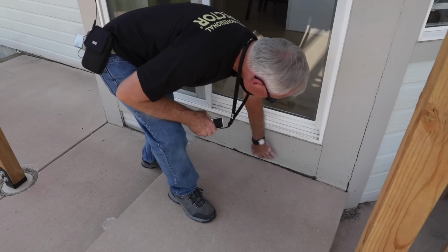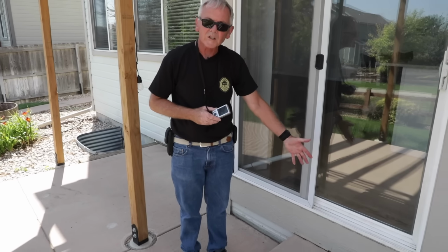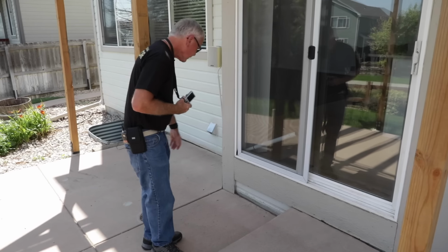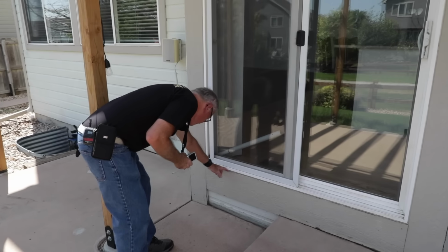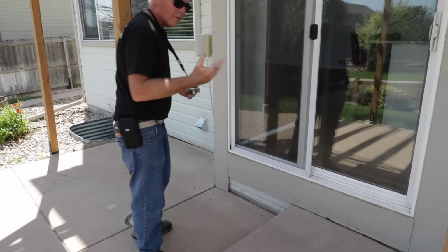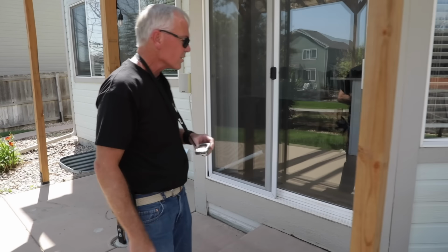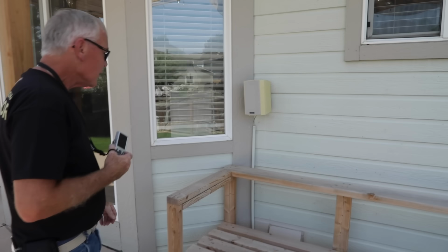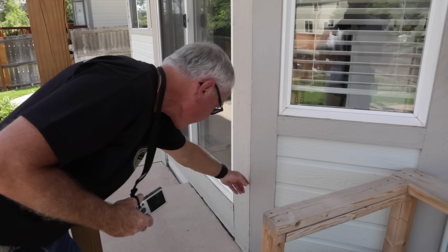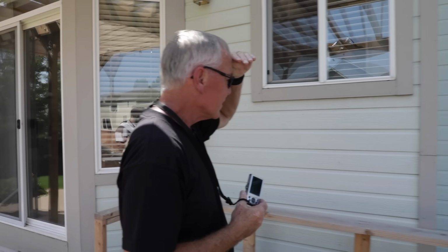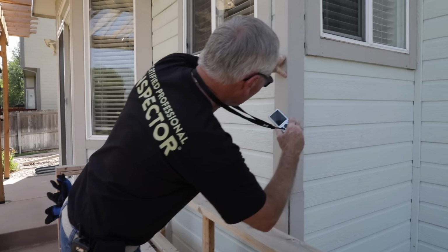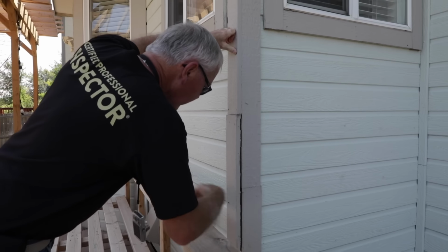What I'm doing now is just checking some pretty common spots where you get some water damage, and one of them is usually this trim piece right below the patio door. And I can see that we've got some peeling paint, failed caulking, so I'll probably just put that in with my note that I'm going to have about all the caulking to be replaced. I want to make sure all these gaps, like here in the corner, get those filled up with caulking. Got some more loose trim here. We'll want to get that taken care of.